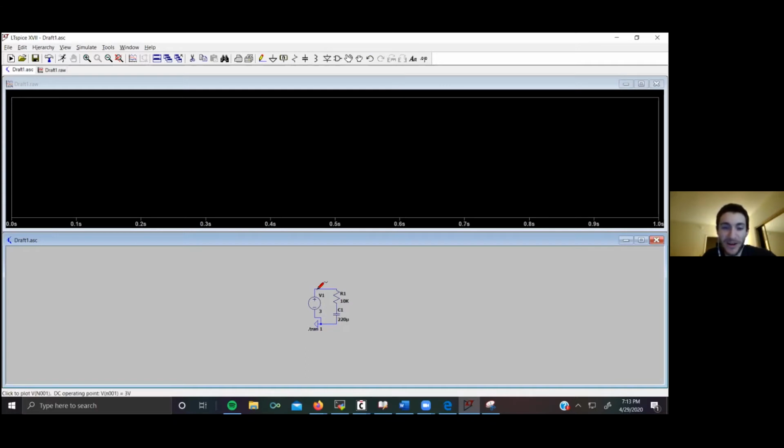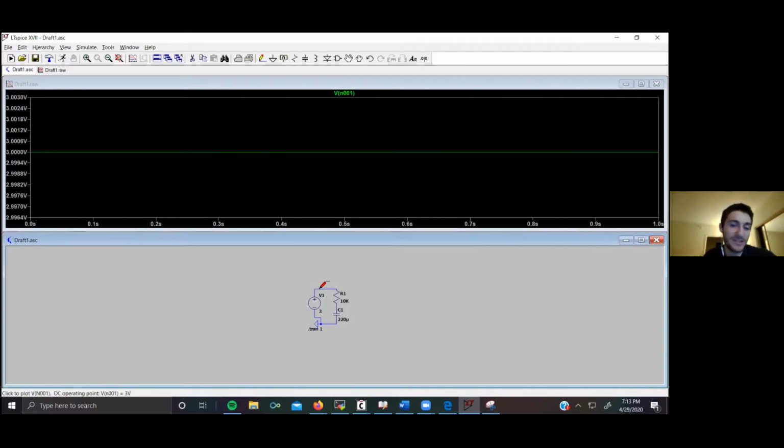So to get the plotted data, we actually have to go back to the circuit and then select the thing we want to see. When we click these net components, we actually get voltages, while if we tap the actual components, we'll get the currents across them.